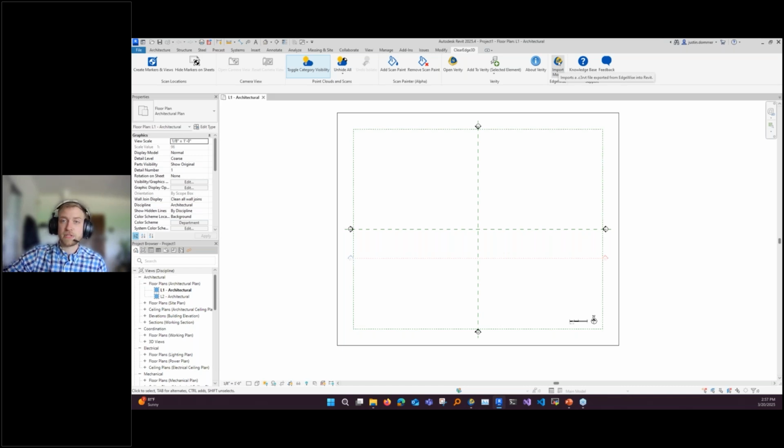But the other thing is this one is much more flexible for only importing exactly what you need on the fly and not importing everything. And that's a thing with the old plugin. The current one in the software imports all the geometry all at once no matter what, which is not ideal for some scenarios. But we're basically importing geometry like our Revit family objects and filling in the details. The recommendation is to switch those out with your preferred families. But it isn't based on a template. It's actually dynamically pulling in the Revit family objects as they go.